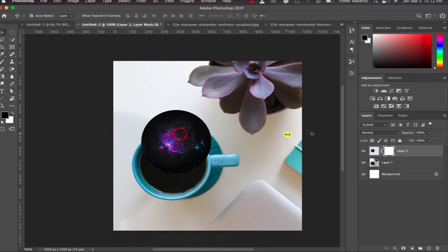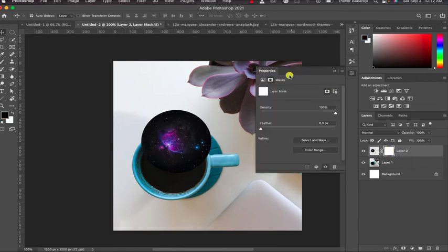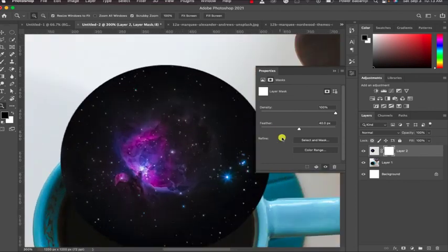Once the mask is selected, you see mask, and you can now do what? When you click on the mask, I double clicked it, you see the mask, and the next thing you can do is increase this feather. Now that feather, what does it do? It adds a soft edge around the image you're trying to create to make it look blendable with the environment. You may not see it much on this, but I just give it maximum.